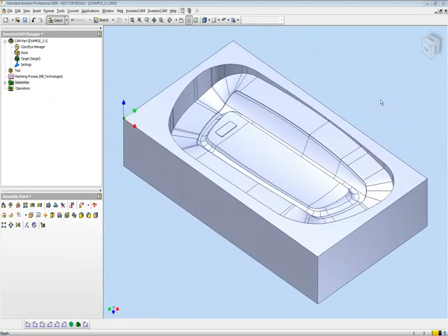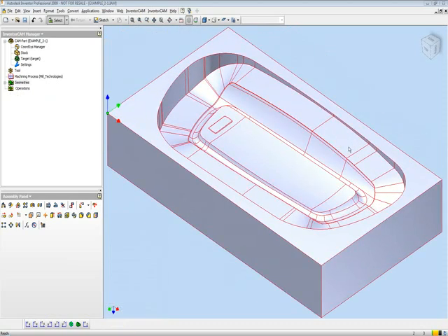Now in this part, what I'd like to do is actually machine these surfaces around over here, and I want to machine them parallel to this curve on the edge as shown over here. The other thing I must look out for as well is that when the tool gets close to the edge, it does not gouge into these walls itself. For that we have a powerful gouge checking option which is not available in any other program.